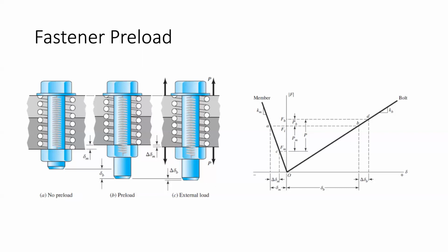And we're going to talk through some of the actual mechanisms behind how fasteners work. If you look at the left side of this image, you have two materials, this lighter gray material and this darker gray material, and a fastener. In this case, they just have a nut on the other side that supports this bolt. As you tighten the bolt more and more, you develop an axial force along the bolt that compresses these two systems.